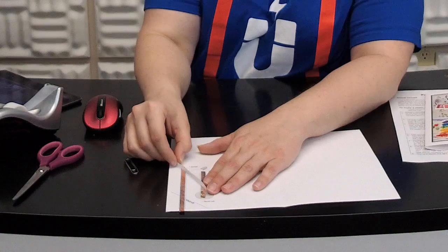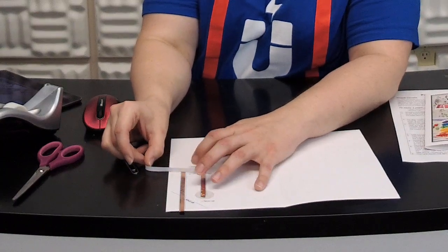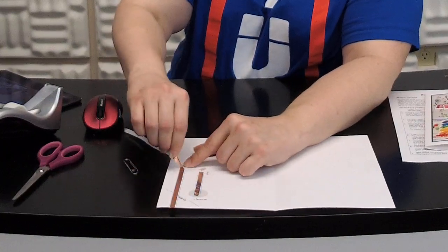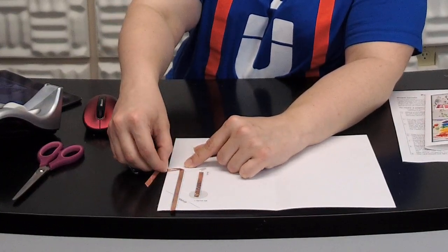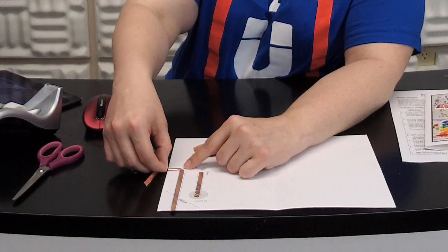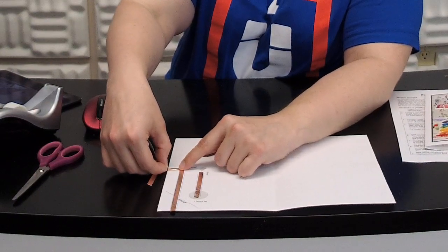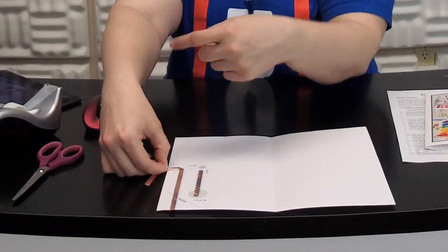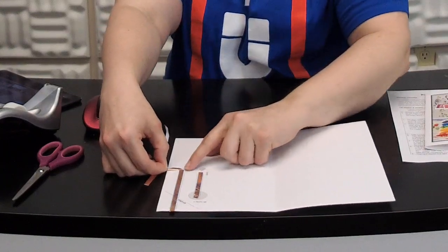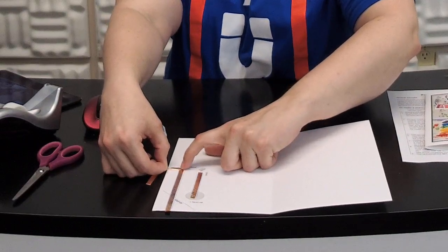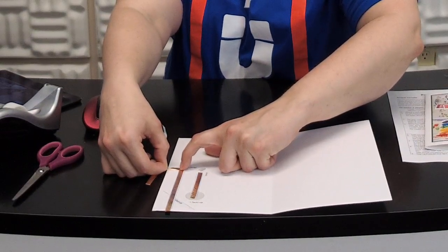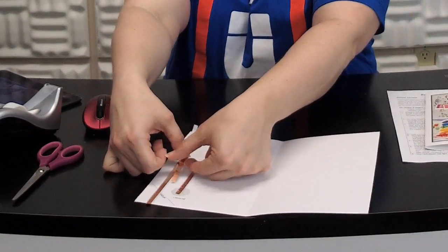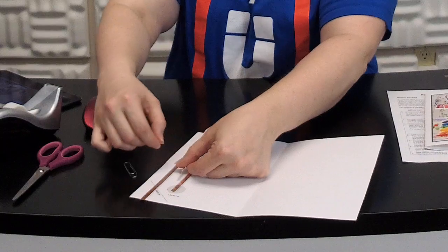So what I'm going to do on my card is peel a little bit of the backing off. I'm going to go right to the edge where I need to stop. Then I'm going to pull my copper tape carefully in the opposite direction that I need to turn. So I want to go this way with the copper tape, so I'm going to pull my copper tape to the left. And that's going to create a fold. Then I'm going to just use my fingernail and very carefully press that copper tape down and fold it back on itself.